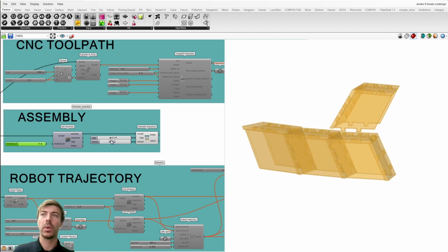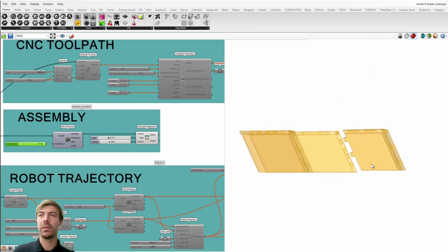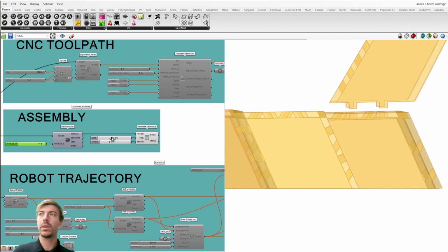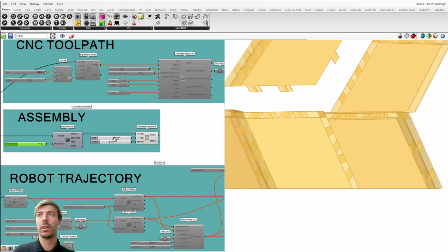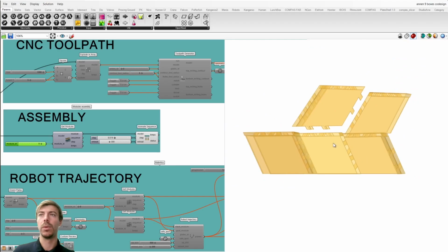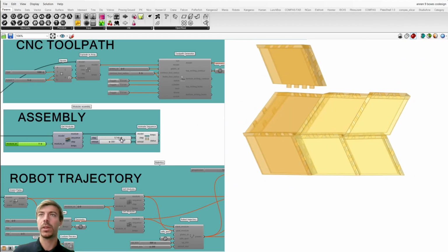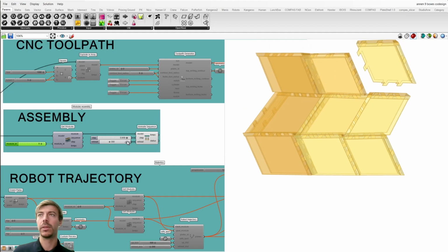And so you see that when they come laterally, here we computed an insertion vector that is perpendicular to the plates. And so when it comes on top, we have a 90-degree tenon angle, while here it needs to be computed between two previous boxes. So all the joints are automatically computed with this plate model builder.